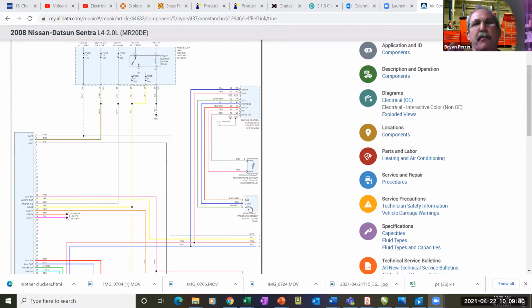What concerns me, were you able to put any refrigerant in at all? I don't think so. I don't think you would. Well, if you couldn't get any refrigerant in, you're still under vacuum, your pressure switch would be reading correctly. You should have been able to fill that thing to probably 80 to 90% at ambient, with 134A, filling it with the engine off once you put it under vacuum. So I'm wondering if you had a Schrader valve stick, or if the adapter you guys were using didn't work right. I've seen all of those things happen.